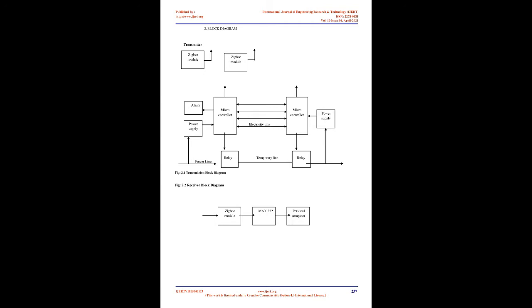There are many kinds of relays, but in all the relays there is just one coil. Some relays have 4 switches, some have 8, but the coil is always 1. But the coil specifications may differ, like some relays have coils of 5V, some of 12V, and they also differ in DC and AC. This specification is always written on the coil you are purchasing.